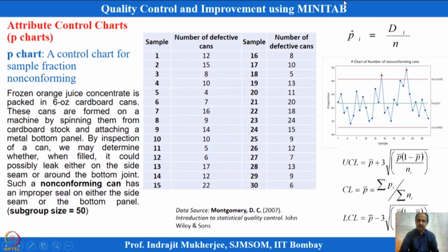Beyond this, we have the P type of control chart over here. That is the P chart and the NP chart, and we will discuss both. P is the proportion defective which is monitored. The earlier case was defects; this is defective, and defective means a 0-1 condition: either it is useful or it cannot be used. So, in this case, either useful or scrap we can think of.